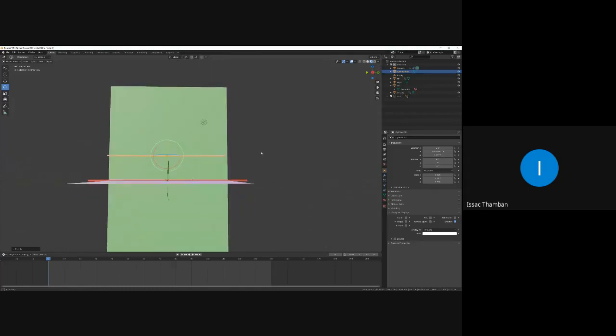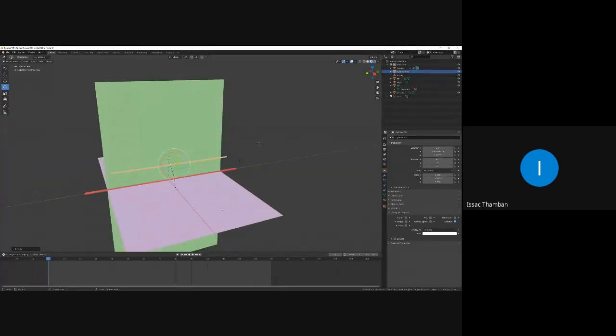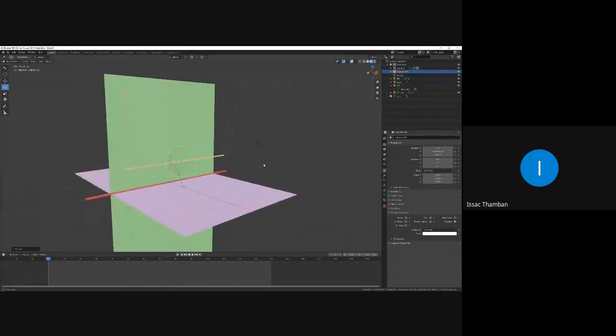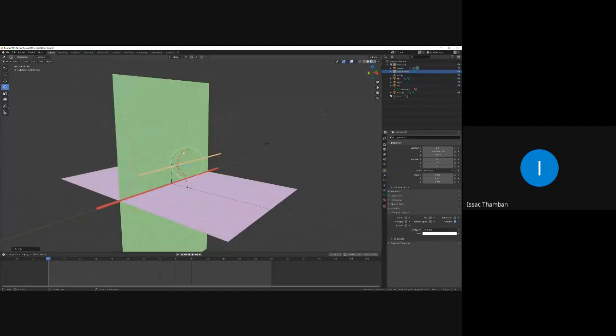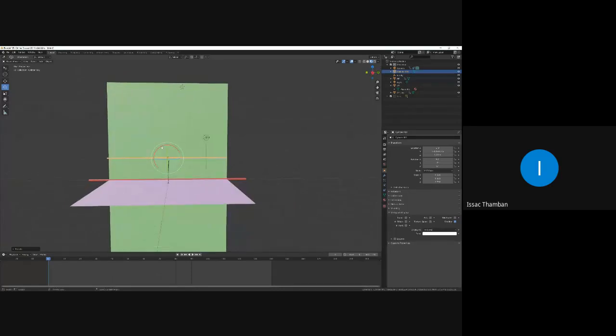After this, we will tilt the line with respect to ST. In the question, it is given that the line is inclined to ST by 45 degrees, so let us tilt the line by 45 degrees, pivoting the midpoint.